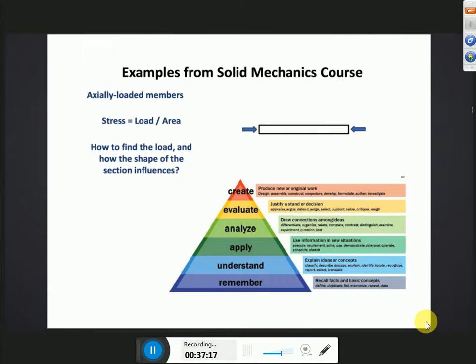And then the load is connected to what kind of load is acting. It could be fluid load, could be mechanical load. There's nothing like a concentrated load in real life. Distributed loads, gravitational loads like self-weight, and so on. So that's the load. And then the geometry is a length, an area. Now, if we just give two numbers and then solve for the third one, that's at the lowest level. Most examples in old textbooks used to be: give any two out of the three variables.